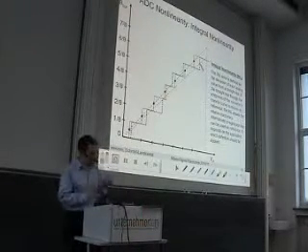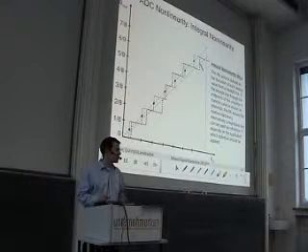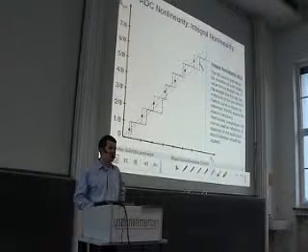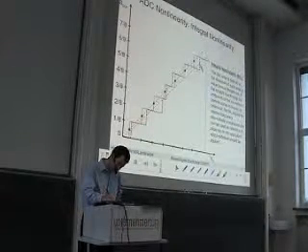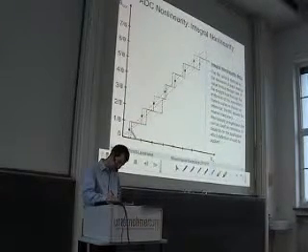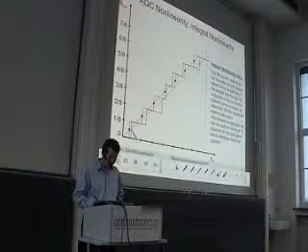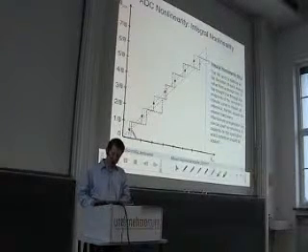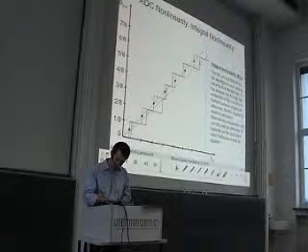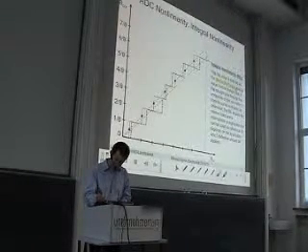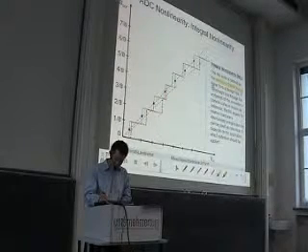Or again, you can say, I take all these points, I compute a regression line and take this one as the reference. Here, for simplicity, we take the one that connects the first and the last point. And now the integral nonlinearity is defined as the deviation of each analog step from the straight line.